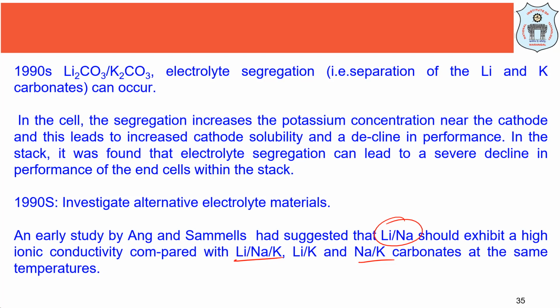All these observations, particularly the issue of cathode dissolution into the electrolyte, were addressed by researchers, and in the late 90s they did a lot of research to find some alternative electrode material. Okay, and that's why they tried so many material combinations of lithium sodium, lithium potassium, or sodium potassium carbonates at the same temperature.